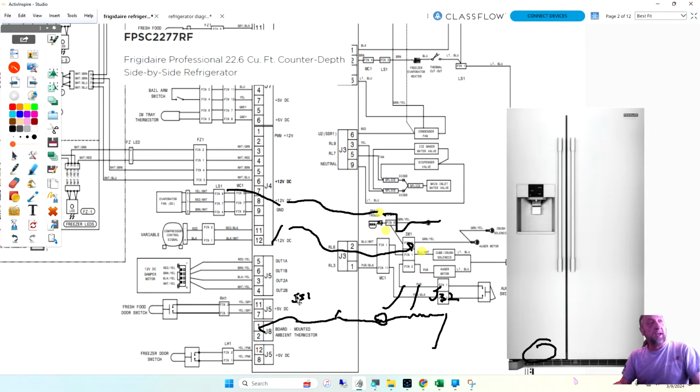and stuff. I had a friend of mine call me out, saying his fridge wasn't cold enough, and it was a side-by-side just like this one here. It was a Frigidaire, as a matter of fact, and the damper is located up top inside the refrigerator.